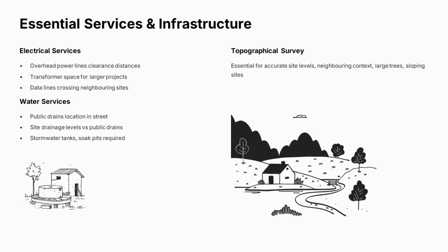Stormwater management and runoff are mandatory in many parts of New Zealand. Your project might need stormwater tanks, soak pits, or water reuse systems. Usually, this means bringing on a civil engineer for assistance. Council websites and district plans can give you an early idea of what is required. Also check for existing underground services on the site. A free service like Before You Dig is really useful for that.